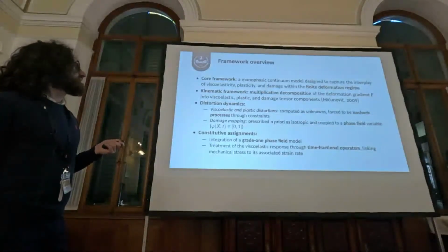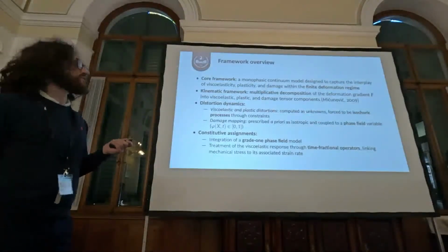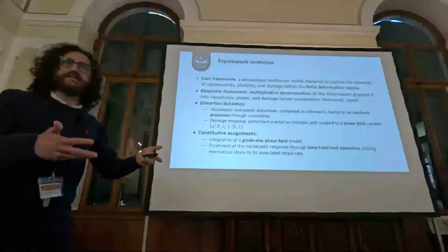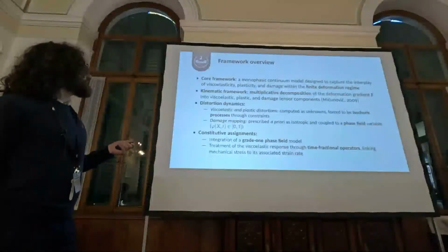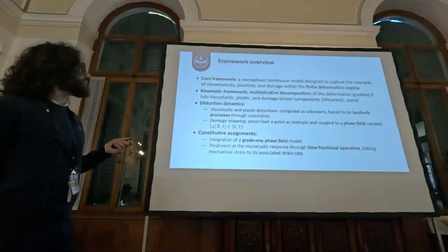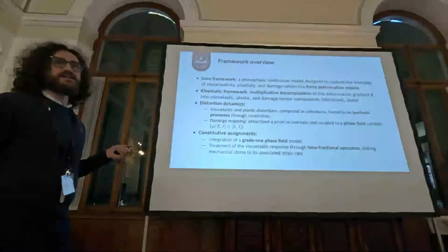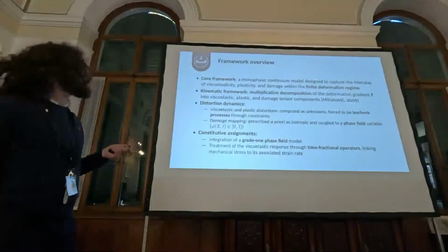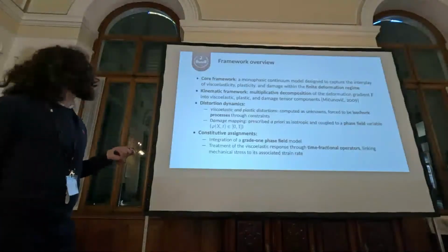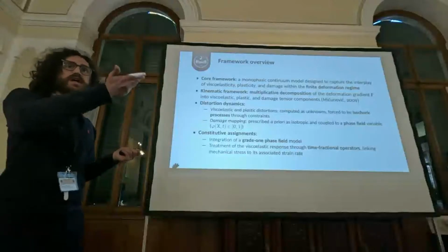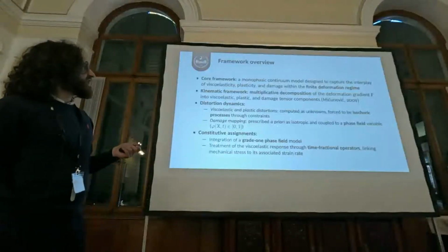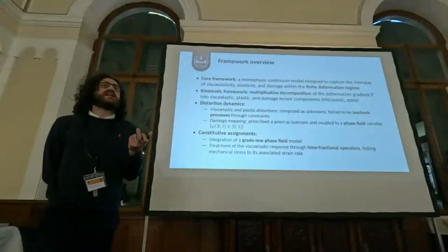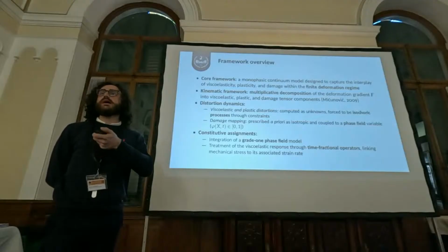The viscoelastic and plastic distortions will be computed as unknowns of the problem, and they will be forced to be isochoric processes through proper constraints. Whereas the third tensor of the multiplicative decomposition, the damage mapping, which expresses the distortion related to the damage process, will have an expression that is prescribed a priori, and it will be furnished in the next slides, and will be isotropic and coupled to a phase field variable that will represent the unknown related to the damage process.